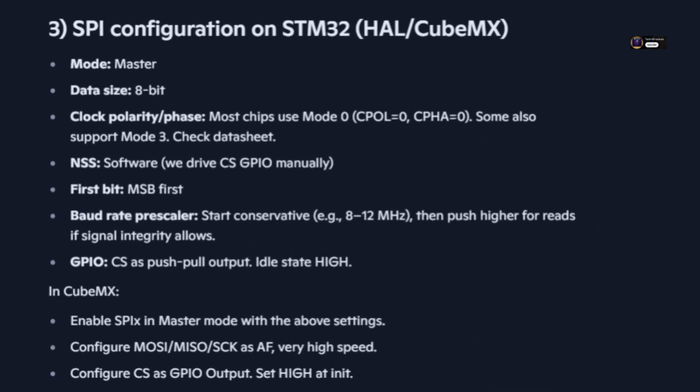Okay, so it's wired up. How do you tell the microcontroller software what to do? Good question. You need to configure the SPI peripheral on the microcontroller. If you're using something like an STM32, you might use their CubeMX tool, which is graphical, or write the code directly using their HAL library.